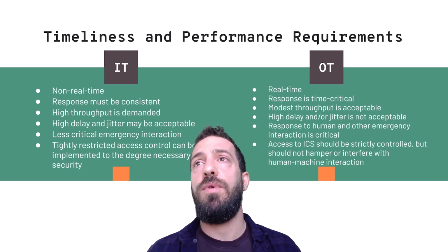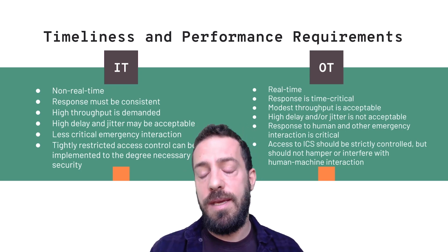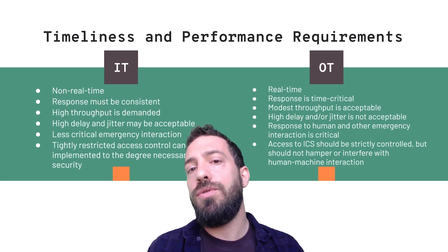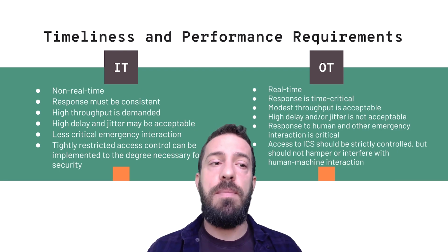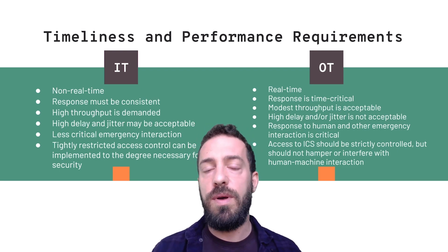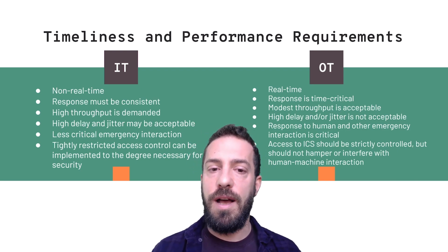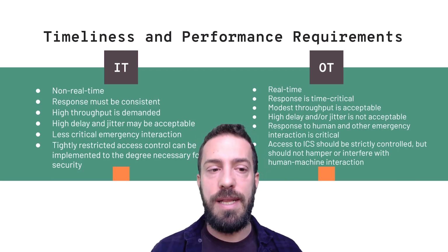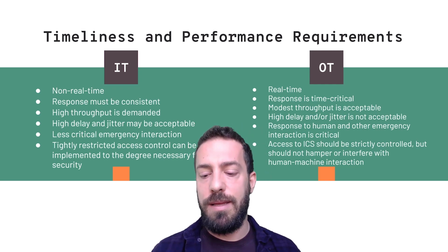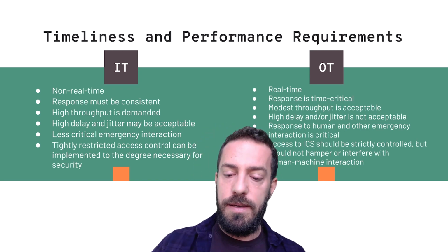You have to think of other ways, right? Instead of deep packet inspection in the control environment, probably a better solution would be to ensure at the boundary that the periphery is secure, right? That the malware will not go into the control network, so you won't have to do further action in detecting with deep packet inspection, right? You can maybe do other things, but that's an example of what should be avoided on the OT side.